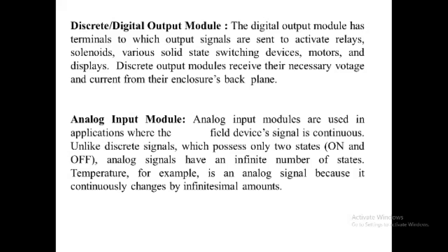The power section of an AC and DC input interface converts the incoming AC voltage from the input sensing devices to a DC logic level signal that the processor can use in the read input section. I'm repeating this: it is the read input section.